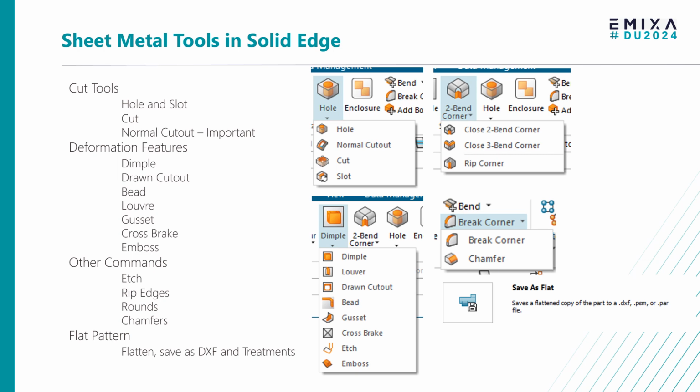One thing I do find that you have to be aware of is that we've got all of the full part commands for holes. So if you put a counterbore hole in, if you put an 8mm counterbore hole, you might end up with a 13mm hole, because that's the counterbore diameter rather than the thread. So just be very careful with that.